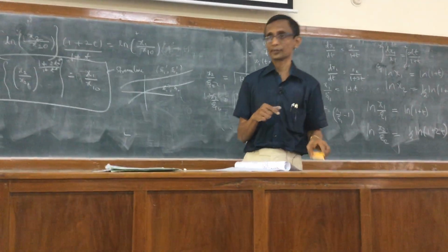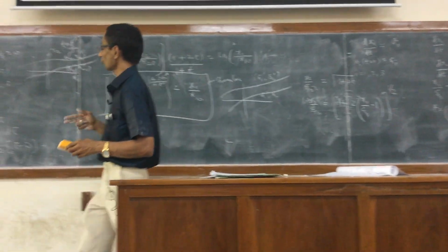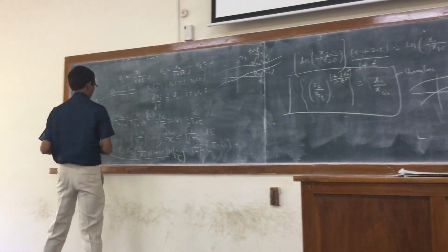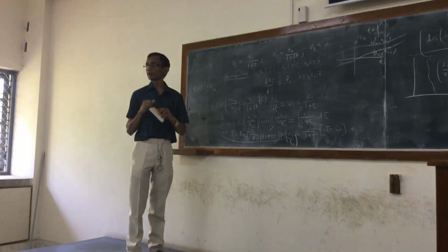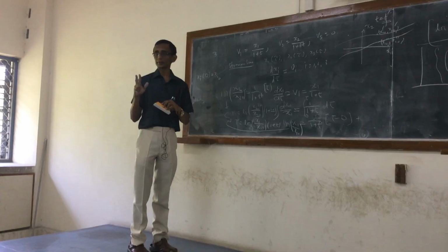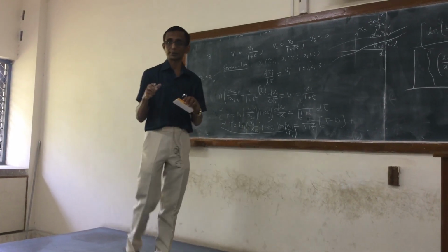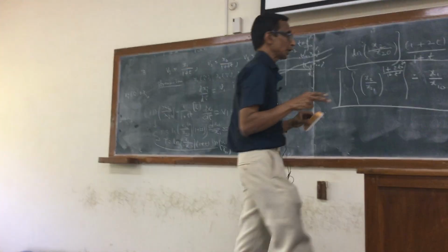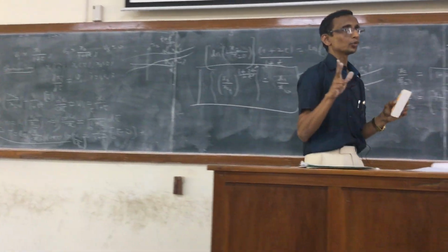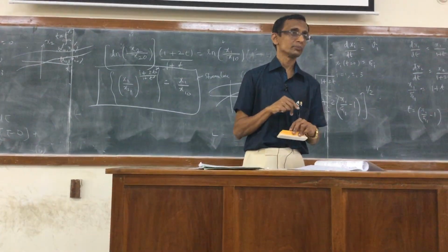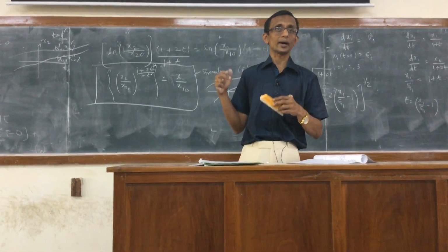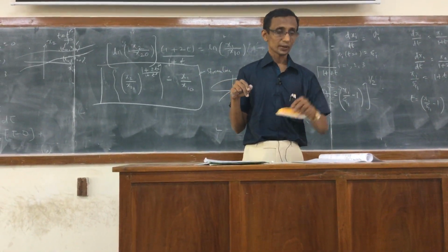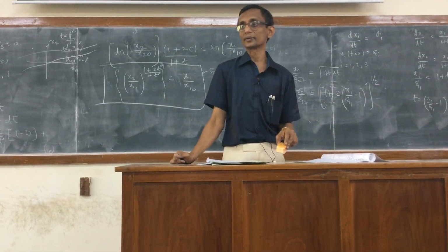In the earlier case we saw, which was somewhat untypical, the streamlines and the particle paths coincided even though it was an unsteady flow. That is not necessary. But in general, the typical case is that the two will not be the same. For steady flow, you should be able to prove theoretically that the two will effectively be the same. So if you plot one of them, you will get the other. Are there any questions on this?